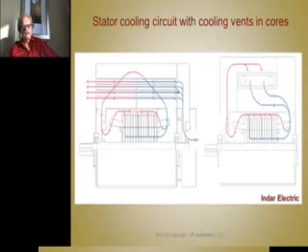This is external air going through a heat exchanger. These are used in these big power plant generators, or no, I'm not thinking of power, I mean wind turbine generators. Yeah, you'll have an external fan that will blow in here, and it goes through this heat exchanger, and the forced air that's forced through the vent ducts goes through this heat exchanger. Sometimes this is actually hydrogen or nitrogen that's pumped through here, and then it's cooled through this heat exchanger with outside air.